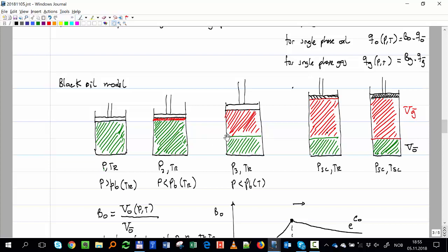So far we have considered that that gas is always expanding, and it's always only gas, gas, gas that is growing, no problem with that gas. Sometimes what might happen is that that gas starts to go back to condensing, starts to condense liquid when I expand. And that is seen using the phase envelope.